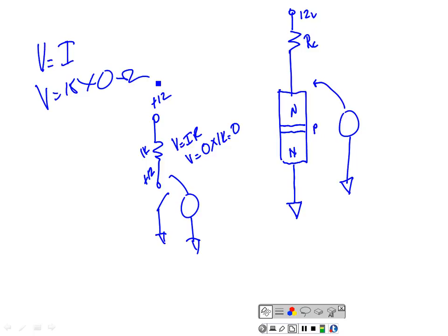And there's ground in there. You stick your hands in there and get your fingers up against that ground running through there, because the yoke is grounded, so the yoke can't get a charge on it. And you're going to get your butt what? Shocked. If I measure across the open switch, it's going to measure what? It's going to measure the applied voltage. Y'all understand that? That is a basic law you need to understand, because if you don't, you're going to get shocked. You get across some high voltage, like 200 or 300 volts, you're going to get killed, right? Or you're going to get burned real bad.